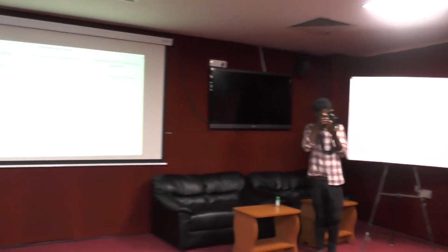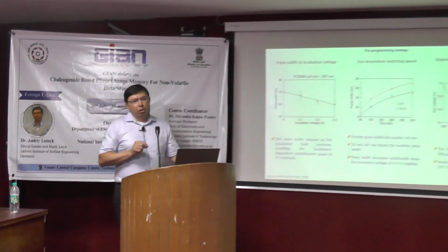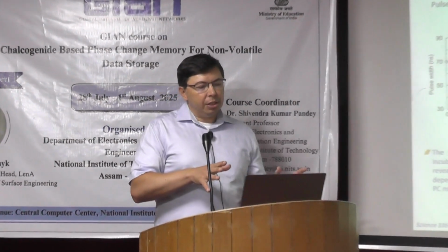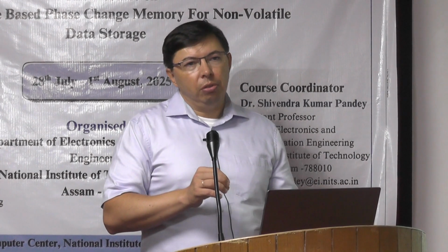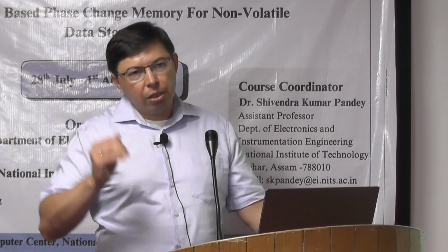Sir, this is regarding the pre-program strategy. Would not the pre-program pulse, hence the pre-program ordering, reduce the amorphous state resistance, hence the resistance contrast? Yeah, but it's still enough. Here we use one big cell, so it is not a big deal to reduce the resistance of the cell a little bit, because the cell still stays in the amorphous state with a little lower resistance than as deposited.